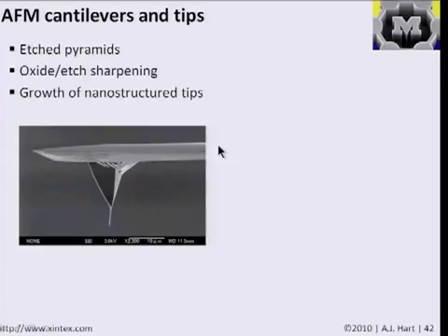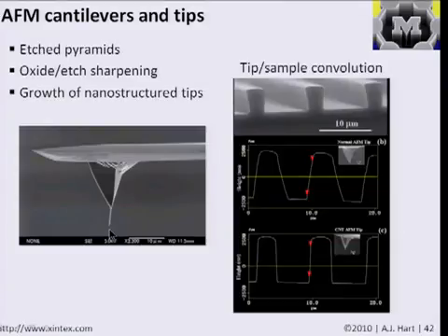And so there's a lot of technology to microfabricate these sharp tips using silicon wafer fabrication and growth and etching, and also adding things such as nanowires or nanotubes to the tips of these cantilevers. And this is an idea where if you have a very, very sharp and high aspect ratio tip, although it's in practice quite fragile, you can then image physically very, very intricate features. And that reduces what's known as the convolution between the tip and the sample, kind of the same idea I was trying to show you over there with my fist and the hole through the nanotube model.